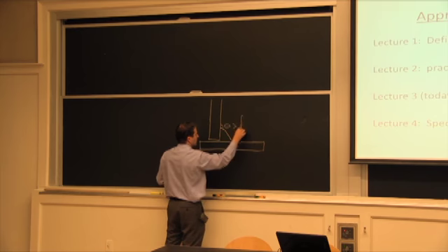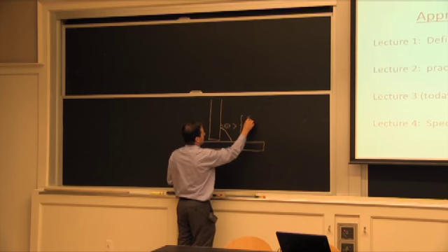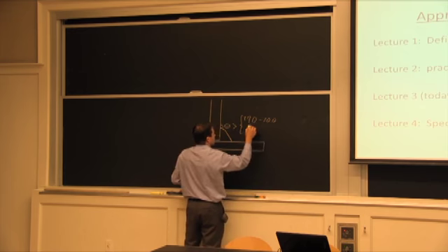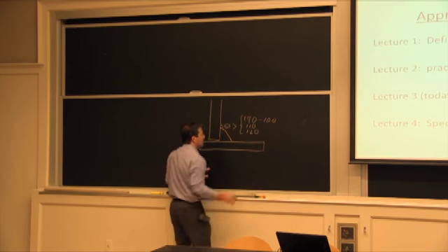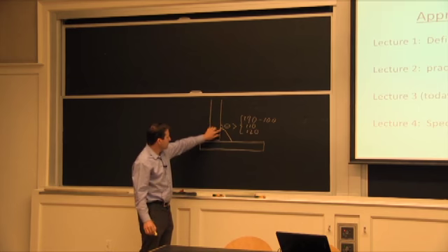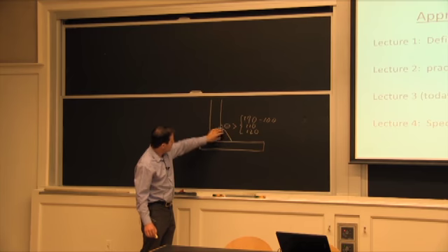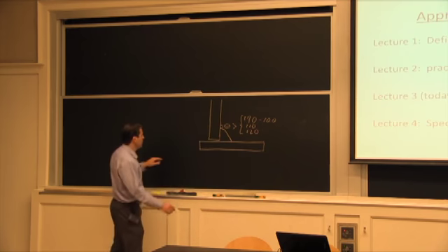and then they have three different levels. If it's the lowest quality inspection, they say it's going to be greater than, is it 90 or 100? I'll put a question mark, but it's either 90 or 100. It's not very precise. Then you have 110, and you have 120. The idea is, by looking at it visually, you can determine whether you had enough heat when they welded to fuse enough of and heat up this metal, so the contact between them.